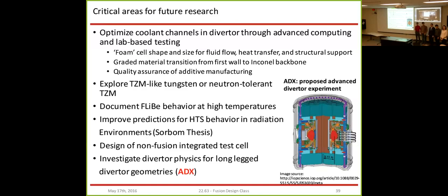Yes, so on these coils, we have 3 on the top and 3 on the bottom, so a total of 6. We did thermal stress calculations and thermal analysis, and we calculated that each coil is going to consume about 25 kilowatts from ohmic heating. We determined that 20 kiloamps is necessary to respond to a 2% change in the plasma. Concerning the voltage necessary for each, I don't have it in mind.